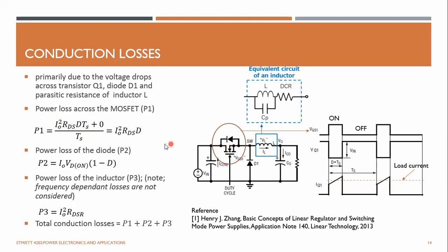the power MOSFET. So if you want to get an efficient system, you always have to find a suitable power MOSFET which has the lowest RDS on resistance. Typical values you can find are 10 milliohms to 60 milliohms or 100 milliohms. So it is always better to go with the lowest possible RDS on resistance. And I squared R involves the square of the load current, which you can't control in the design. And based on the duty ratio also, your power loss increases, right?